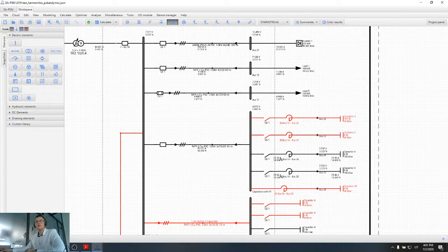I can see that you have provided quite a lot of questions while I was giving the presentation. Let's start from Mr. Osman. The question of Mr. Osman was, is the RMS voltage value with harmonics always higher than the fundamental voltage value? Actually, not too much. Normally, RMS value is not very much affected. Maybe if we consider very sensitive measuring equipment, we will find this increase in RMS value, but it's not very much affected by higher frequency harmonics.